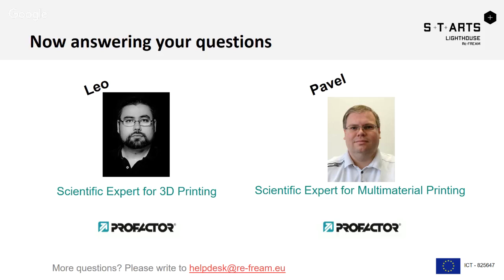If we need samples, yes, because the textiles are different, and we usually have to planarize the surface of the textile to be able to print on it without soaking the conductive material into the textile, which then reduces the resolution of printing, for example, for integration of electronics. So it's definitely better to send a sample to us, and we can try to do a test print on it.